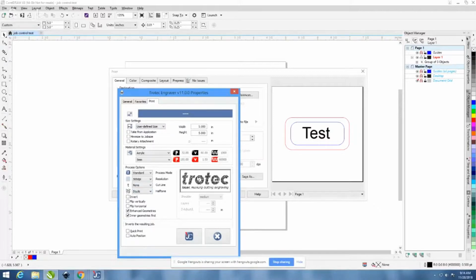The other one that's on there is the Floyd Steinberg. I find it to be a little on the dark side. So if you're engraving on something like anodized aluminum, you can use it. But if you try to use it on wood, for instance, I find the results aren't very good. There are too many pulses, and you tend to end up blowing areas of the wood away. So you tend not to get the same detail as you would on a lighter dithering method like Stucki.